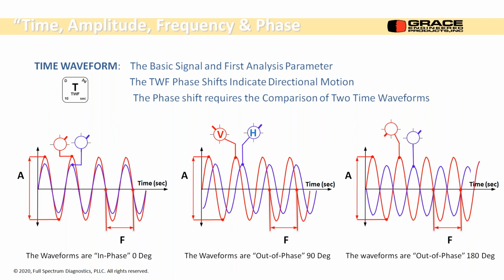There is phase information, and like I mentioned, you can do this manually, or you can do it eventually if we can sync all the transducers. And the best idea of phase is looking across the coupling. So let's say I'm looking across the coupling. There's been an amplitude change. We go and look at the 2 different transducers that are talking to each other, and we note that they're in phase with each other. Okay, their time waveforms lay on top of each other; they're not shifted. Right, that would say that the coupling's in phase, and it must be something else, or not misaligned.